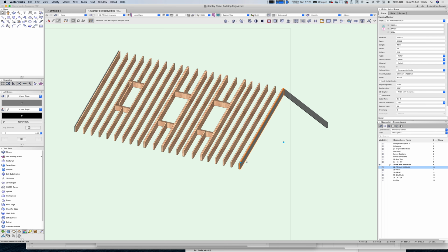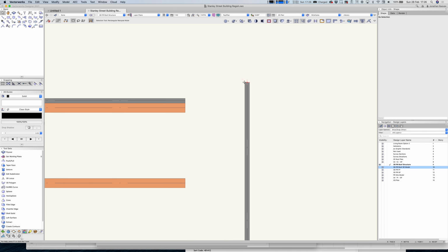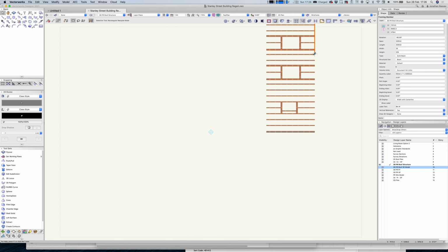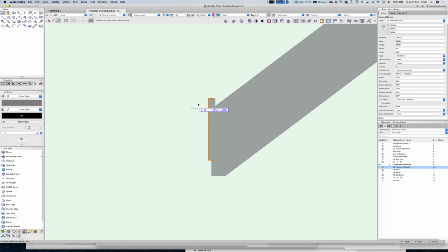Okay, so with a bit more work, here is the roof structure pretty much done for this side. So I'm just duplicating the fascia again, making that into a small solid beam, if you like, and taking away the pitch. And you can see it's a different colour, which is nice. So let's snap that to the side of the roof, so we've got a fascia to apply our gutter to.